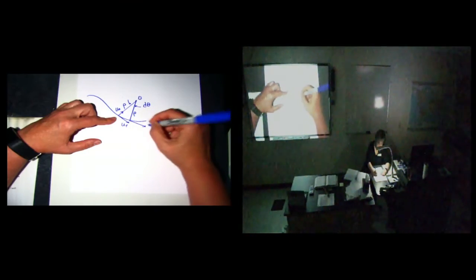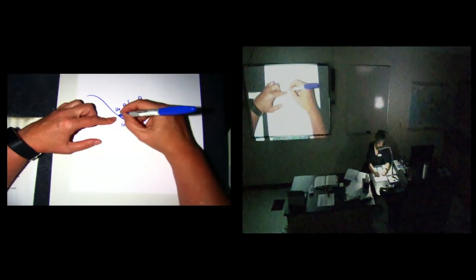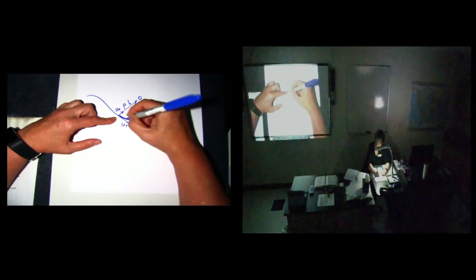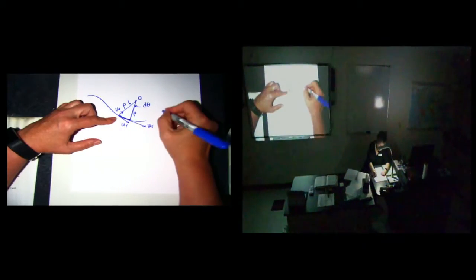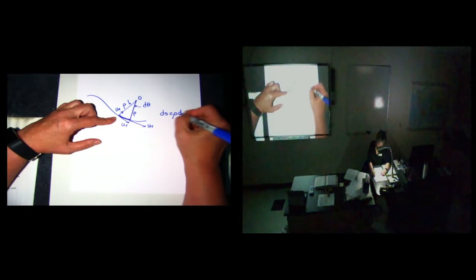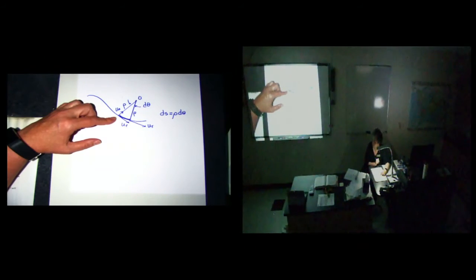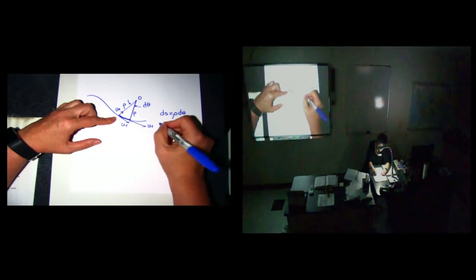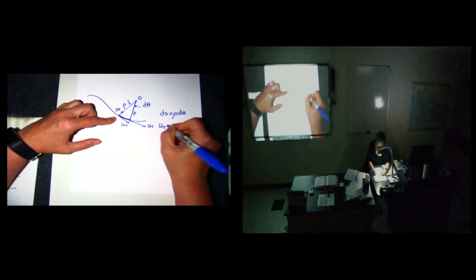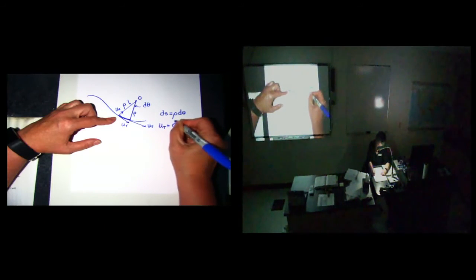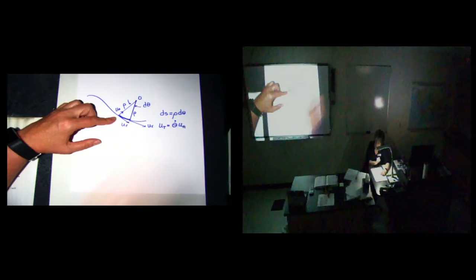And so I end up with an A that looks like this. I get an A tangential with a normal vector, and we end up with AN ultimately looking like V over rho. And we've seen that before. If it's circular motion, we've seen that one before. That's my centripetal acceleration, and my centripetal acceleration is V squared over R.